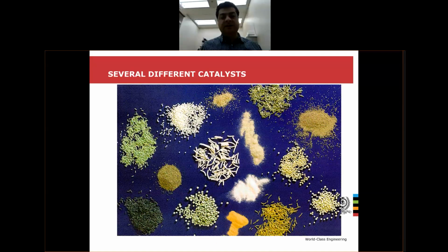So, in terms of catalyst, you have different sorts of catalysts, either in the form of powders, granulars, needles or pellets. You have different sorts of catalysts in multi-phase systems. But usually in fluidized reactors, which we will discuss next, solid particles are quite small. I mean, they are less than 1 millimeter. We will see what type of particles we usually deal with in fluidization.